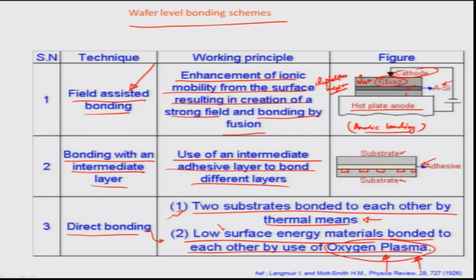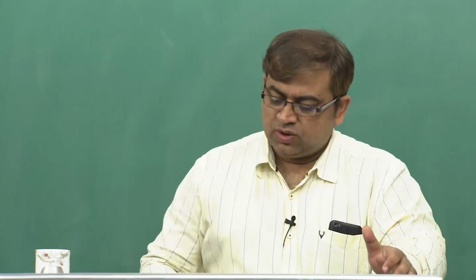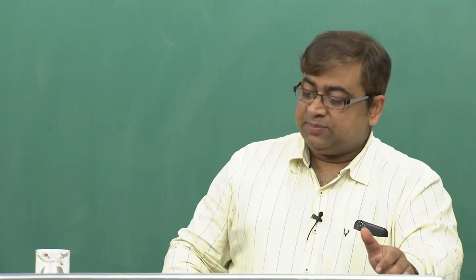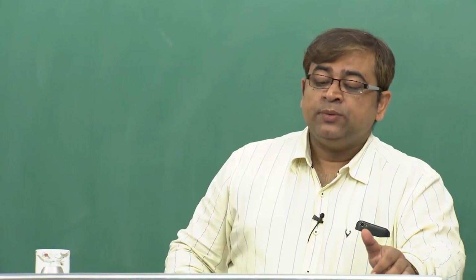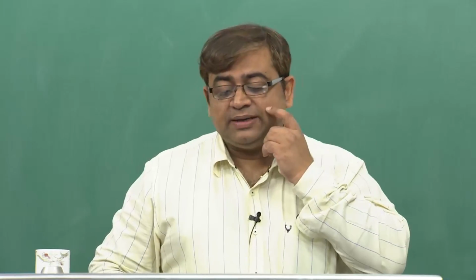Remember, I talked about physical chemical etching, or physicochemical etching, where deep reactive ion etching of various kinds is possible by creating a plasma and driving diffusion of the plasma into the substrate by using a bias voltage. So all these different applications of MEMS would include this oxygen plasma based fabrication. So let us look into the theory of plasmas a little bit.